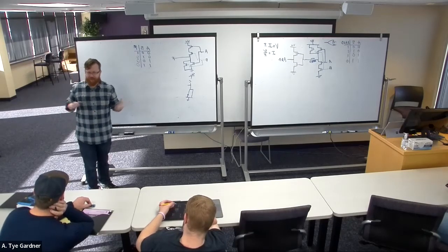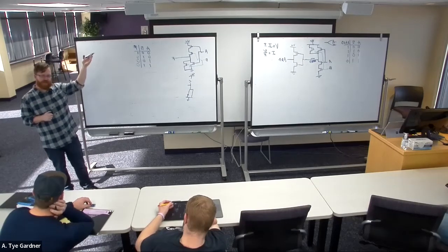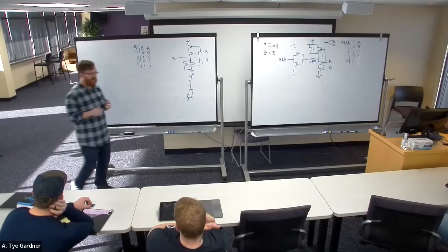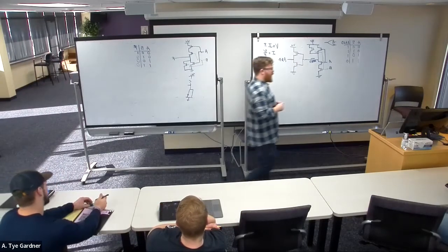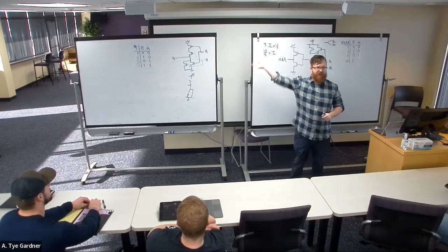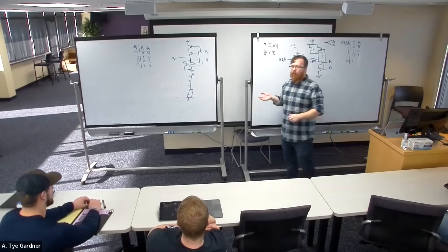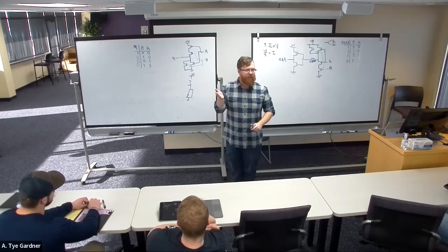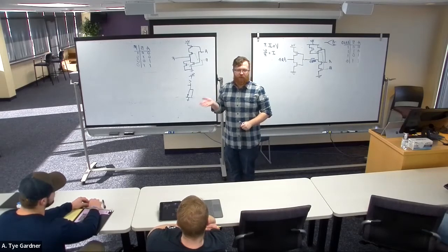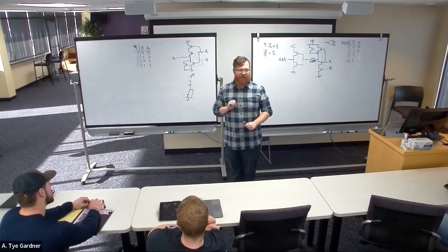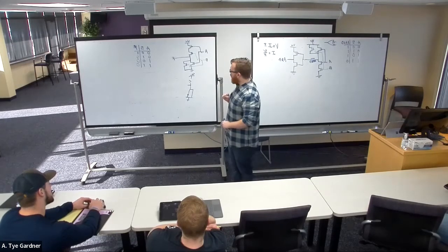So yeah, right. Your intuition served you well, in that you already kind of understood the relationship between NAND and NOR, that they're going to be opposite. And again, if I wanted to make an OR gate, I have to slap on an inverter to my NOR, and I have 6 gates. This is why we teach the bubble pushing, right? Because the circuits that you build using NAND or NOR logic are the minimum size circuits. They use the fewest number of transistors by a significant margin, actually.